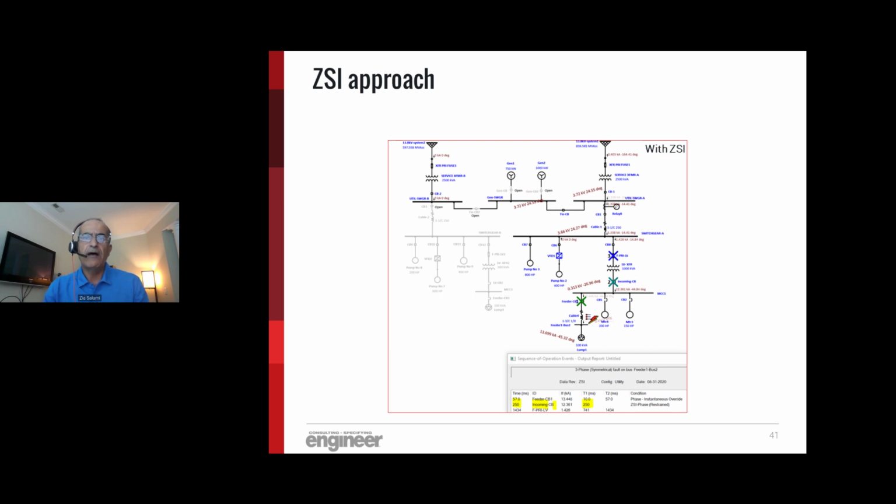And again, that shows that there is coordination, because we are preventing or delaying the incoming breaker if there is a fault. ZSI can probably be one of our top choices, but it requires control cable and hard wiring, so it is maybe a little costlier than changing settings. But again, I think it would be a good mitigation strategy if we can implement it in our facility.